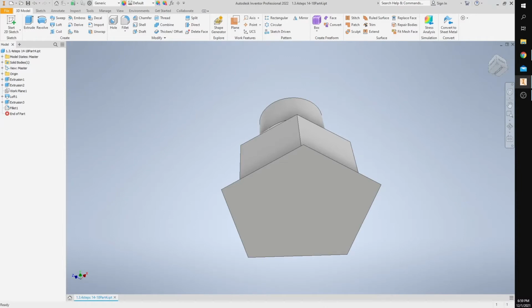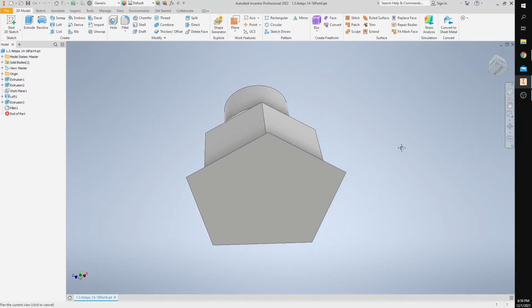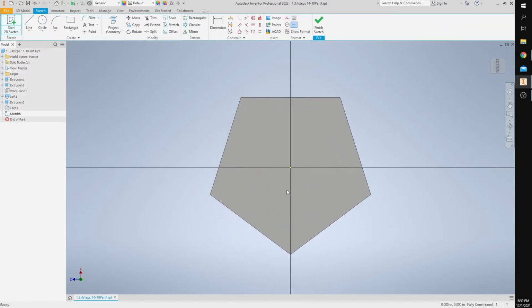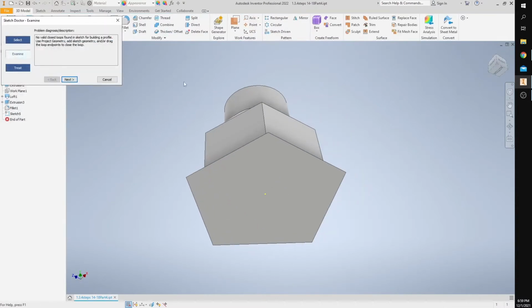Alright, so now we're going to add a short tapered extrusion, which is step 21, to the bottom of the solid model. Approximate a small, almost vertical edge of the physical case, and we're going to use a 3-degree taper. So in the settings, we're going to type in 3 for a taper. And it has to flare out, not in. So it has to flare out. So now on yours, if you can just extrude this part, then that would work. But on mine, and I'm assuming most of your designs are not going to be able to, you're not going to be able to extrude it.